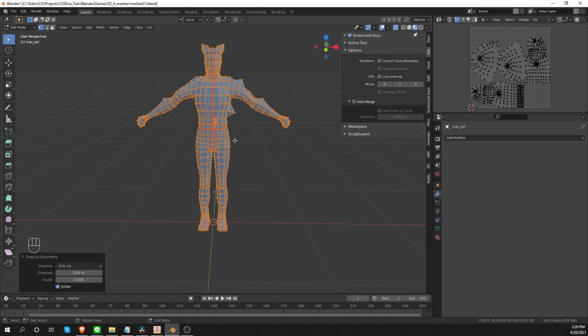This function tries to find vertices where the symmetry was lost and it attempts to fix the symmetry. So in this case, you'll see that it kind of found one of the symmetrical vertices. The other ones were probably too far away from their original position, so the function couldn't find them. But there's this threshold value. If I increase it, I may be able to find them. And so increasing this threshold value may help you fix problems, but it can also introduce errors. So you have to be careful with it.